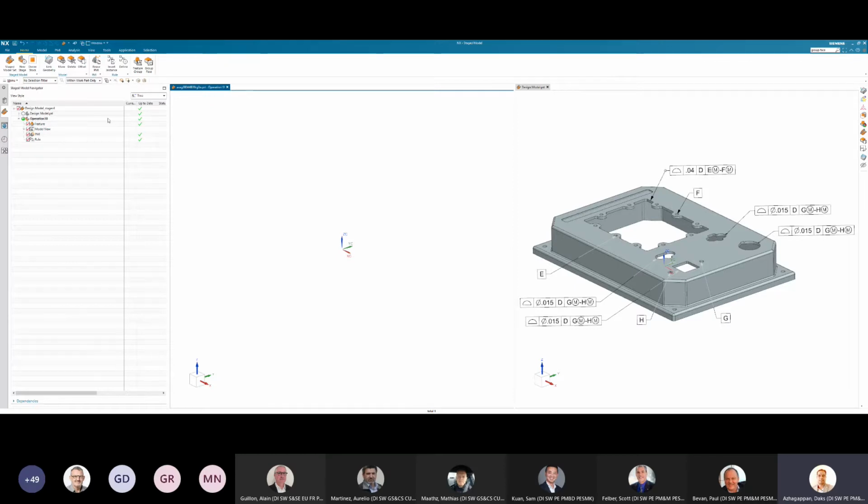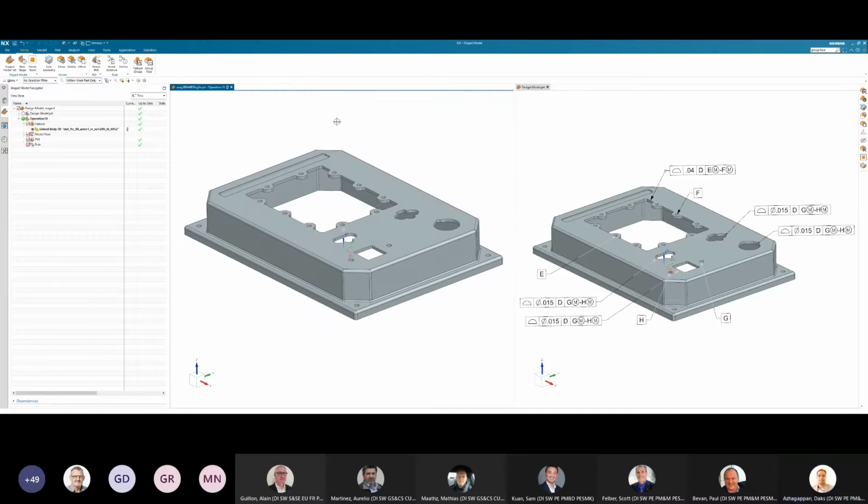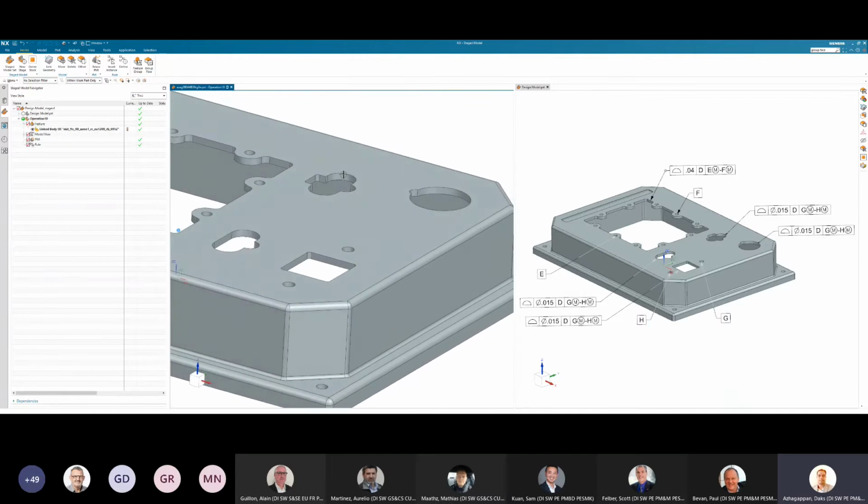So in this case, I could start with the first step of the process, which is to take a reference of the product data. So you can see this. We can link geometries. Obviously you have access to all the information: curve, point, datum, sketches, face, and body. I can start with my product data. So this is my first operation. In this case, what I'm going to show here is that I'm going to be machining, as a final operation, these top 4 pockets that I've identified as part of the description also.